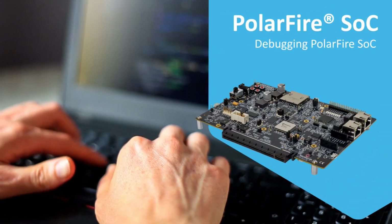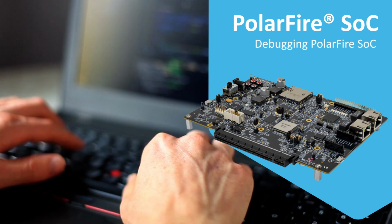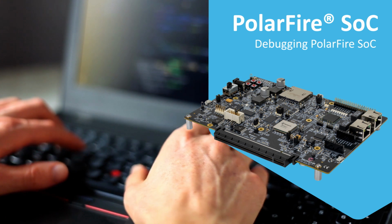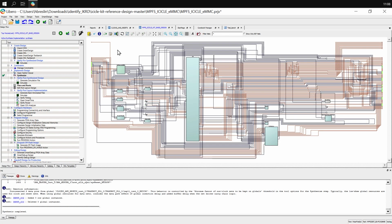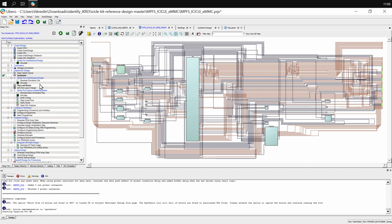In this video, we'll use Identify Debugger to capture a trace of components in the fabric from the Icicle Kit reference design. To begin, open a copy of the Icicle Kit reference design and ensure that the synthesize step has been completed. Once this is done, right-click on Synthesize and select Open Interactively to open Synplify.